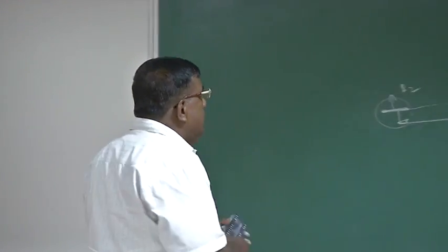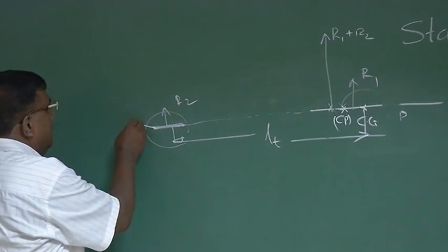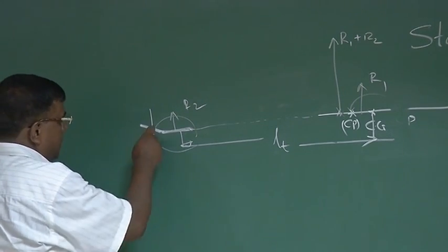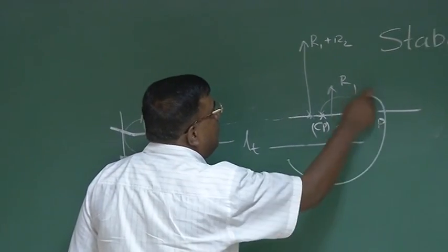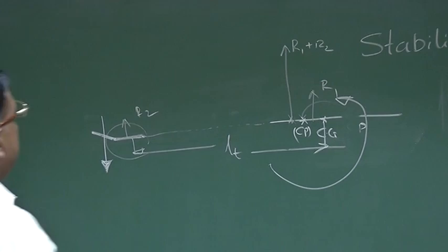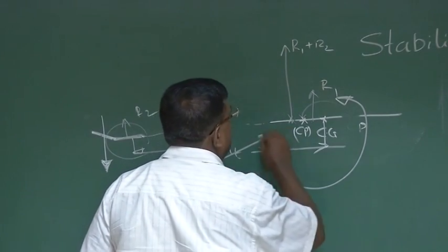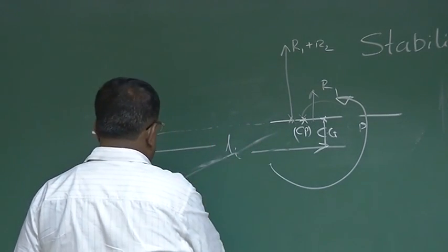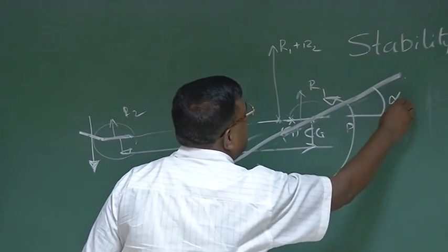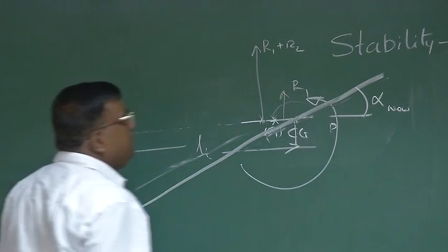So to counter that, I have to generate additional force which will give a downward force and it will give a moment about Cg, and this moment should be good enough, equal to whatever restoring moment coming because of static stability. And if I can make it balanced, then I can fly this whole system at some other angle. That is, I am now flying it like this, some new alpha. This we have discussed, right?